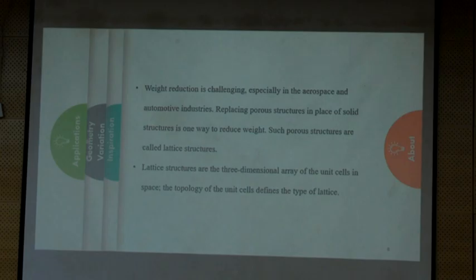The good thing about the lattice structure is, suppose we are getting a material, aluminum, and we are printing it, right? The aluminum properties are the same, stiffness, Young's modulus. Whatever you have designed, that is aluminum, so the property is the same. That will not change. But the good thing about the lattice structure is if I print a different lattice structure, the property will vary. It won't depend on the material. While studying lattice structures, suppose I print the lattice structure with aluminum or some PLA material, we do the mechanical characterization. The Young's modulus is there, right?